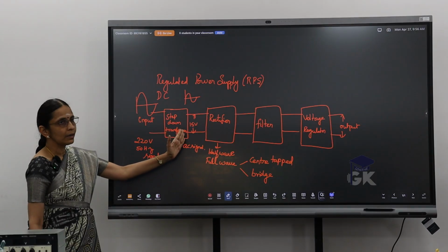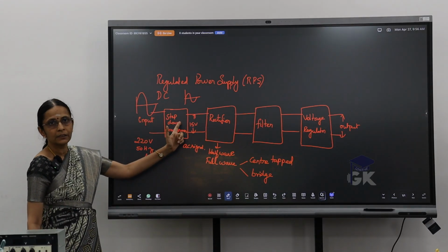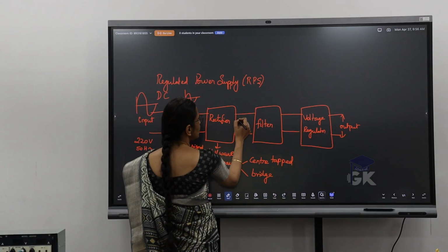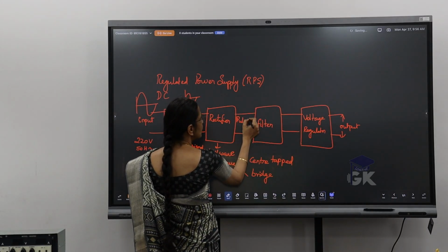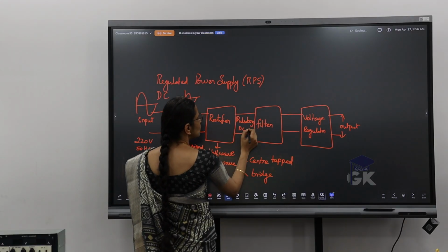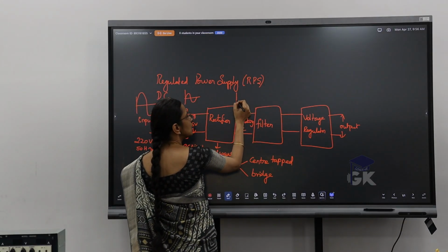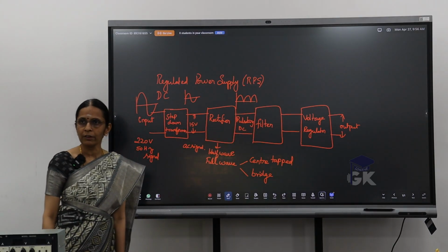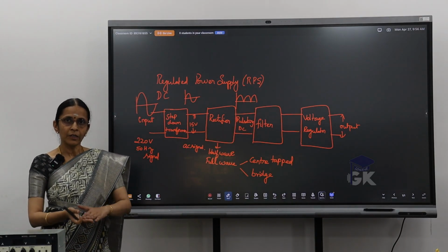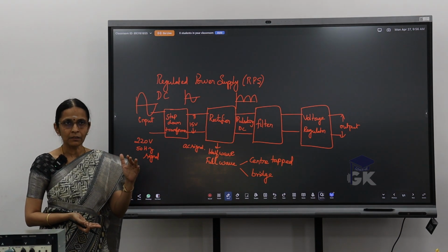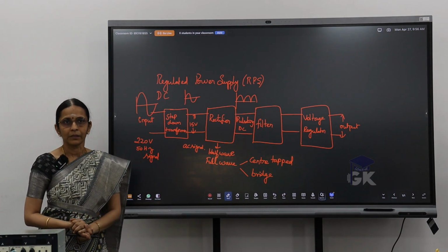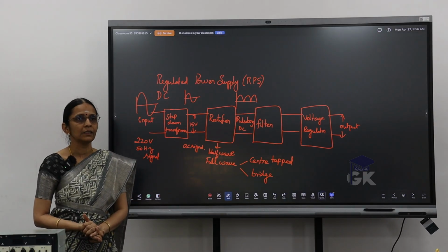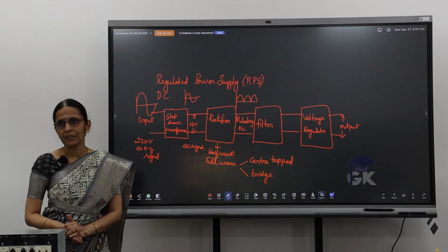So basically what the rectifier does, converts your AC to a pulsating DC. So now what do I have here as the output is a pulsating DC. So what does it mean? My signal is going to be something like this. Suppose if I have used a full wave rectifier, it will be only unidirectional, one direction, but with all the ripples. Okay, with the sinusoidal component still present, or to say my AC signal still present along with my DC.